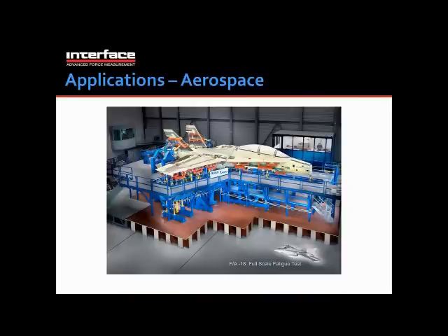Aerospace. Aerospace is a very strong industry for Interface. Every airframe component, whether it's the entire structure or wing assembly, even the landing gear component, needs to be tested very thoroughly, not only for design strength but also from a fatigue standpoint. And load cells are used there in conjunction with hydraulic actuators to not only give the test signal back to the data acquisition system, but also typically to control the hydraulic load, again similar to the material test frame that we saw earlier.